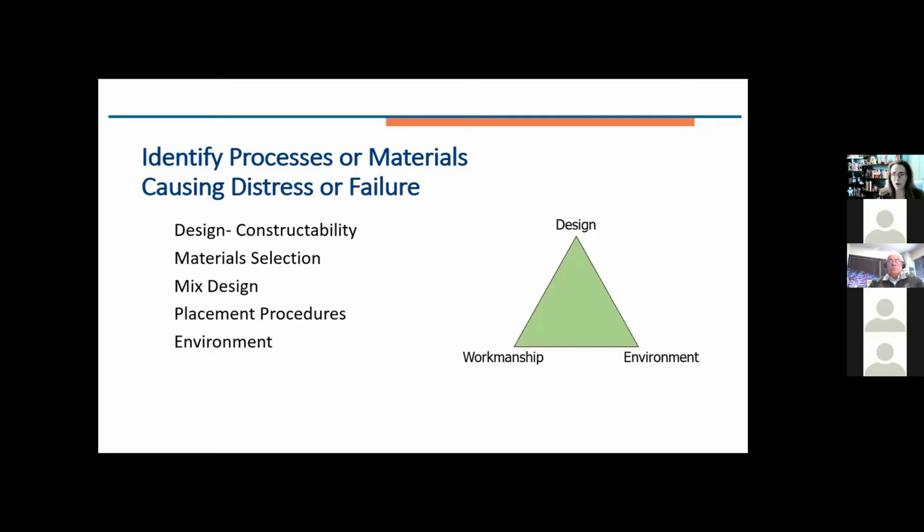But really, the other thing that needs to be considered in all of these circumstances is the environment you're placing it in. And that means not just a freeze-thaw environment or a sulfate environment, maybe you have some reactive aggregates, all the things that you might need to consider. It's also, is it a hot weather placement or is it a cold weather placement? Those things change how the concrete will perform in its fresh properties, and those change how you should design the mixture for that placement.